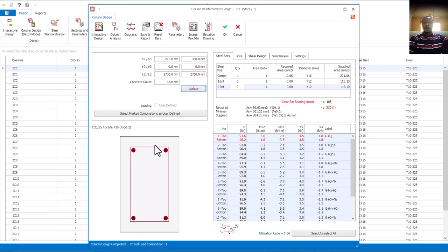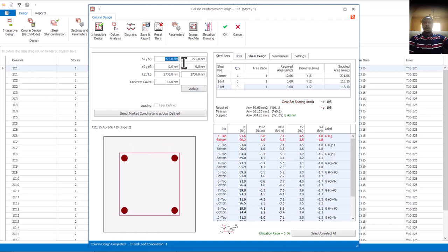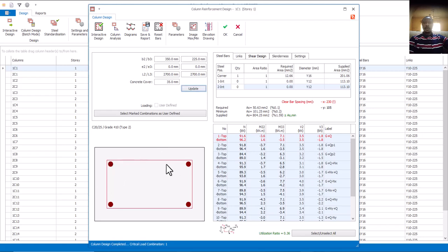If it's along this side, I want to make it, then it's good. But if it's not along this side, this vertical side, I can turn it to X direction 225, then update back. Then come to this place and make it 350, and click on update. Can you see the direction now? Can you see how it is? So when you are changing your column, make sure it's along the wall. Is that okay?